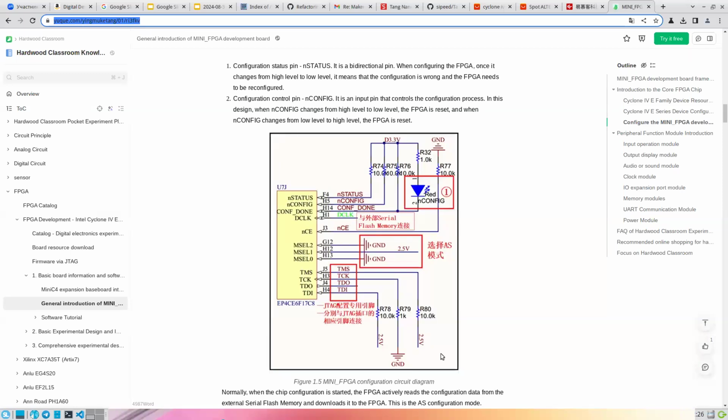So we are using a bunch of such male to female wires, and we just put male here and female here. So this is VGA. Before we start connecting anything, we just need to test this board with some basic examples, like shift register, with gates and so on. So we need to make sure that when we press buttons, it does what we expect.